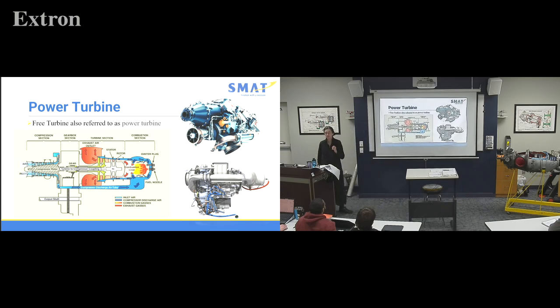Yes. Which part of that's the diffuser? It would be kind of this whole thing, but really, on this diagram anyway, this is where it's widening out the most. So Allison's is a little wacky. On the PT6, it's obvious, right here's our nice little short diffuser. Where the Allison, they're taking it the whole way from here to there. So you could say a whole diffuser section here.